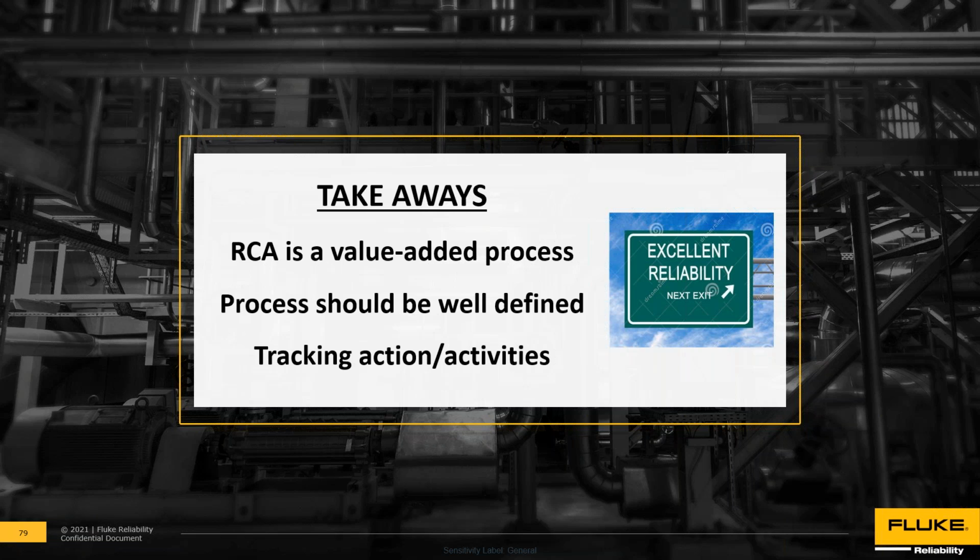One company I was in, every time we had an incident, it was, oh, we need a PM for that. We need a PM for that. And I'm going through all these PMs, thinking, gee whiz, it's a one-time event. It never happened again, and I've got a PM to do one task. It was just a knee-jerk reaction. I would recommend steering away from that mentality and looking at the real root cause and what is a value-added thing, because there are some failures and events that could be considered a one-off.